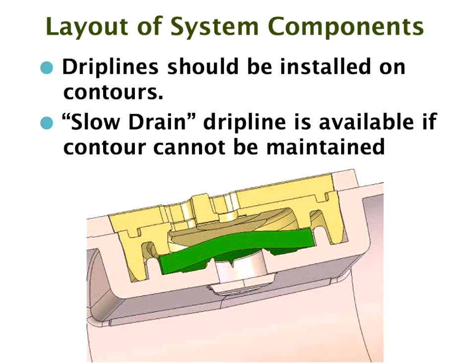And you don't want to keep the pipe full, because there are drippers that will keep the drip line full, and then you have ideal circumstances for bacteria to grow in the pipe, and you've got a problem with bacterial growth, which will, if somebody shuts off for a long period of time, even a few days, they'll come back and find that they have to flush the system immediately in order to get rid of this growth that has taken place inside the tube. So we have a slow drain dripper, which has actually got a slit in it here. You see that slit there.